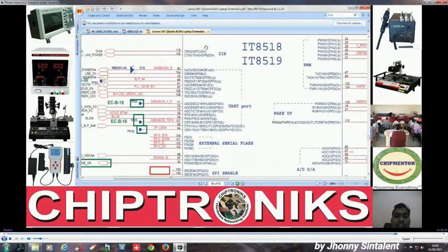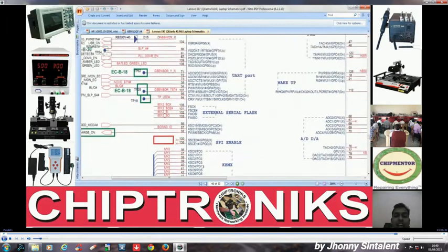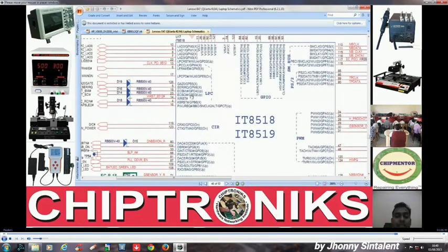As I said, serial IRQ, right? SERIRQ. What it will do is, it will first send a signal, IRQ2. 2 means keyboard. So it will send a signal to the processor, and that will let the processor know that yes, a keyboard command is there. Keyboard command, those data would be sent through these 4 pins to the processor. The processor will read it, and the operating system would convert those two signals into an ASCII character, and it will press that key. That key would be displayed onto the screen.